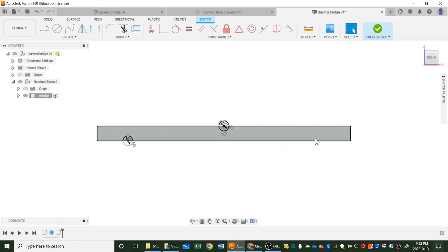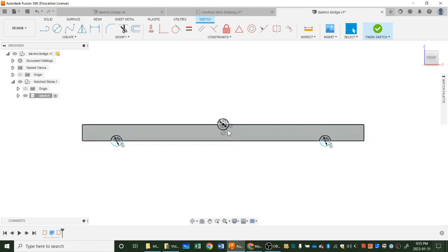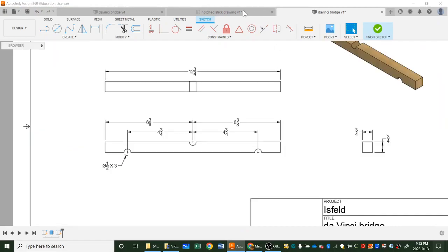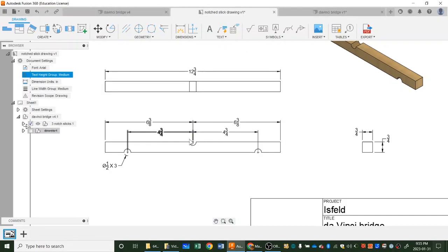And then we're going to head over here and make another one, circle. I use C on my keyboard again, enter. There we go. So I've got circles, but they are not in the right place, those ones. So I have to put them in the right place. I'm going to go reference my drawing again. It says they should be 4 3/4 inches away from the center circle.